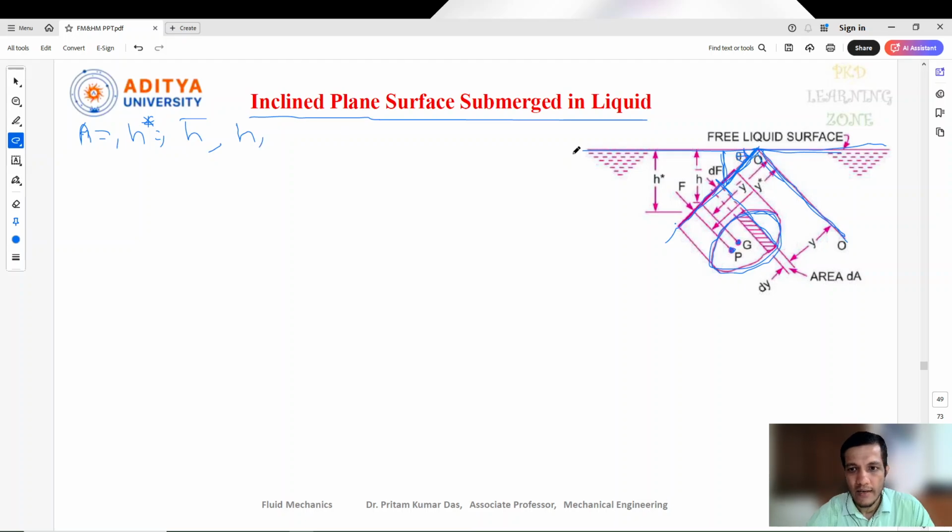Theta is the angle between the free surface of the liquid and the inclined plane. dA is the small area of the strip, and dy is the height of this strip. Similarly to how we have taken H star, H bar and H, we take y star, y bar and y.